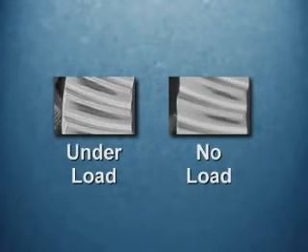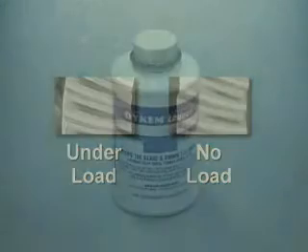There is another issue to keep in mind when assessing the contact pattern. When the gears are under load, the contact pattern will be different than when there is no load. The area of contact will expand on the surface of the tooth. If you need to check the pattern under load, the following method can be used.